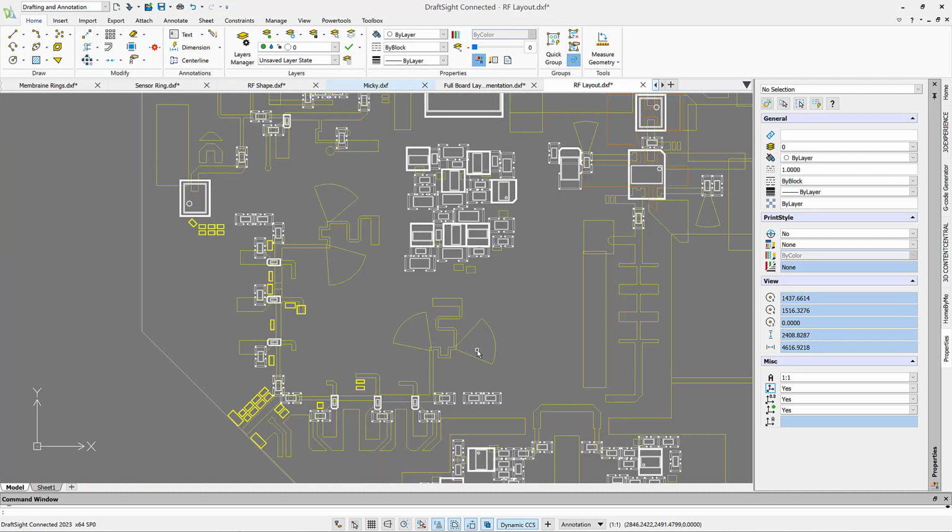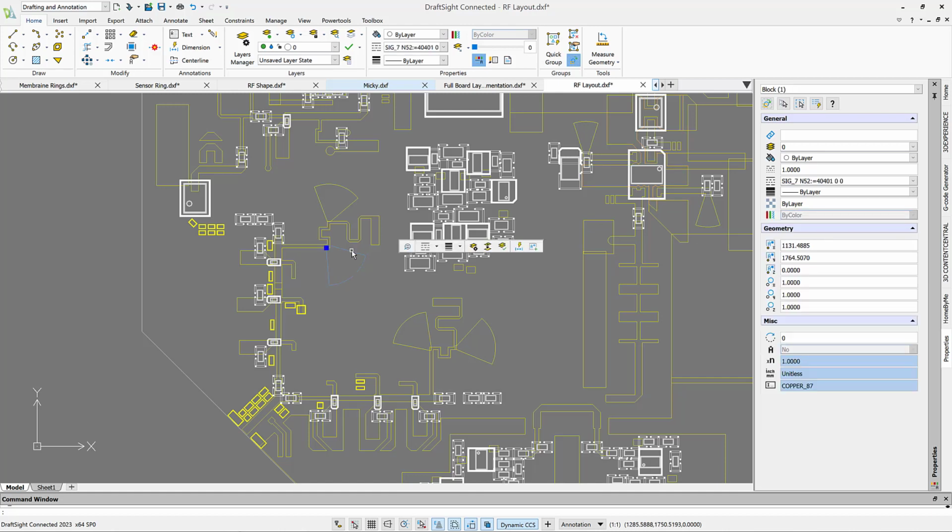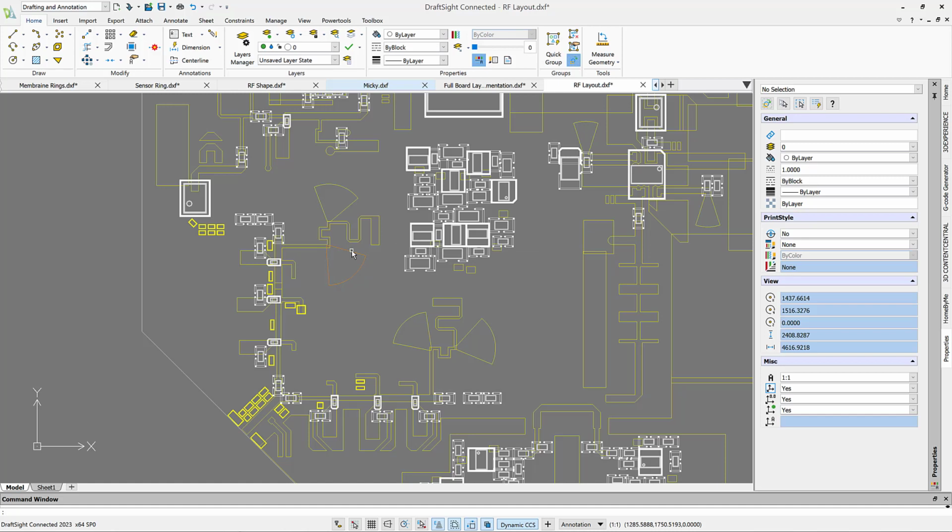And now some other ones, this is like tuning circuits for RF design. So people who design RF boards will immediately understand what I'm talking about and appreciate that we'll be able to bring this in via DXF as a complex shape inside layout, and they end up on specific layers, and automatically you can create the board layout for this specialized RF design application. Not a trivial thing to do if you don't have DXF import inside your PCB layout software, but if you do, it saves you a ton of time.